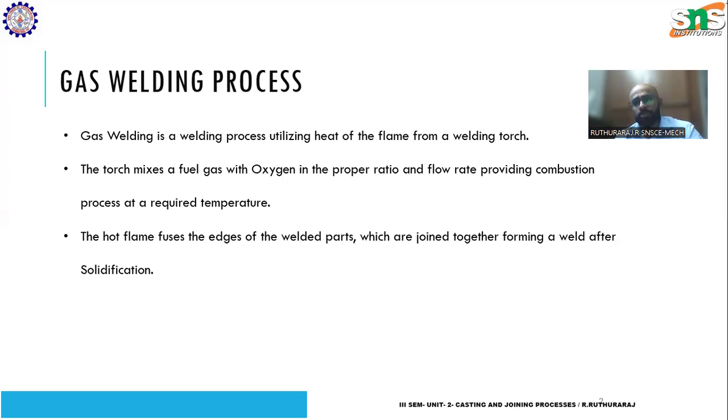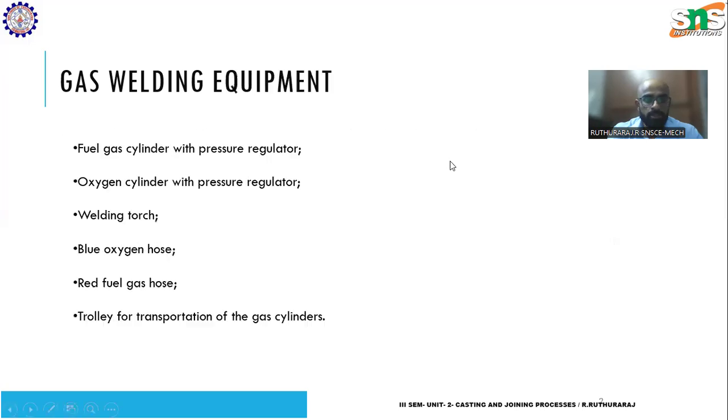How is it able to melt the metal? Similarly, your cooking pot is made up of very thin metal, but how is it possible? It is possible because of the process called complete combustion. We would have discussed this process in your cupola furnace itself. So in the operation of the cupola furnace, as we discussed, an external supply of air is provided to provide complete combustion. Similarly, here also in gas welding, let me explain the process.